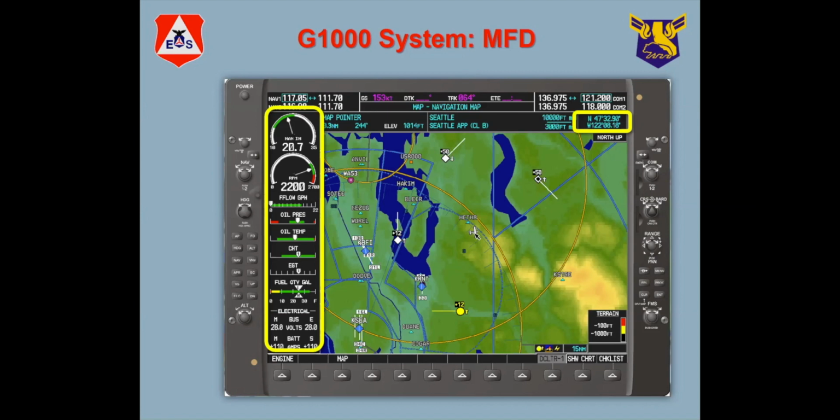Either I will or Daryl, I'm not sure, but it's in degrees. So it's north 47 degrees, 32 is the minutes, and then decimal 90 is tenths and hundredths of a minute. So that's north 47 degrees, 32 minutes, and 9/10 of a minute. That's latitude, and then the longitude is the other number there.